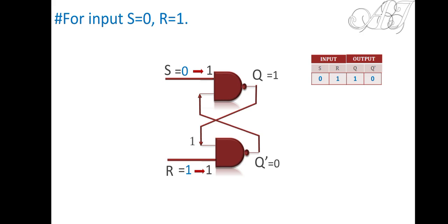So every combinational circuit has its own propagation delay. Okay, what is propagation delay? Let's say I have applied an input, whatever time it takes to produce output. Obviously those propagation delays will be in nanoseconds only, but there is a time. And those times will be different in each case. Even if you take every parameter equal, still you can't design two combinational circuits having the same propagation delay. There must be a small difference, and that will be in the range of nanoseconds only.